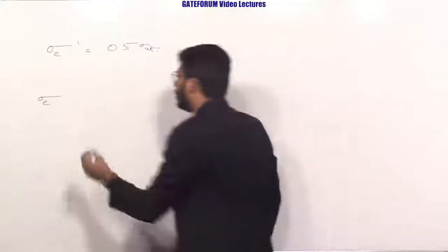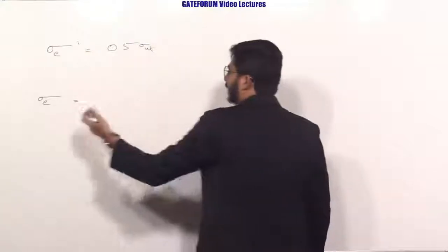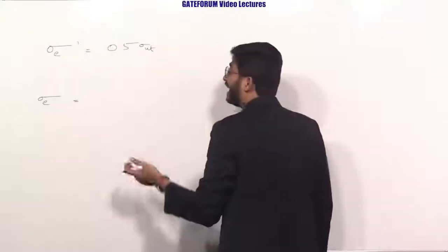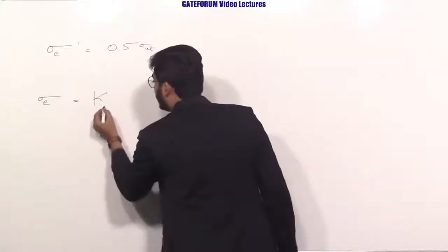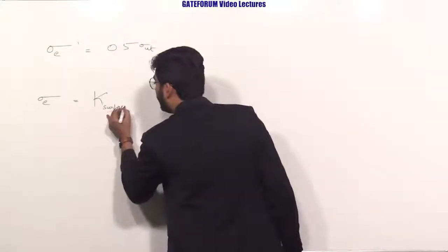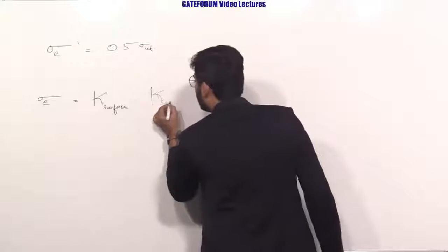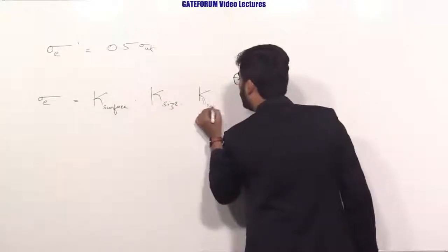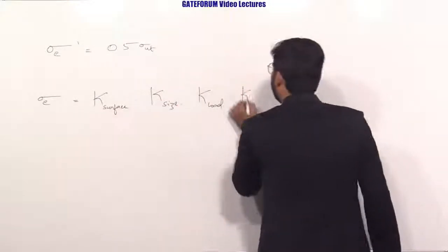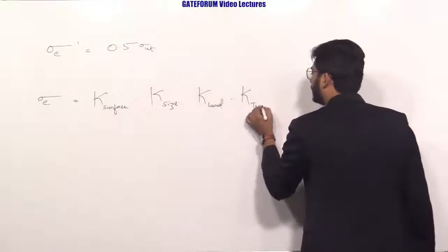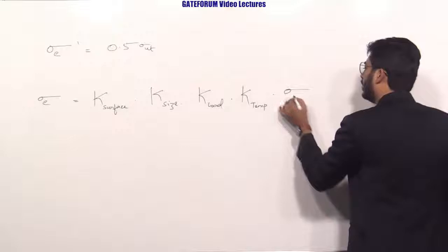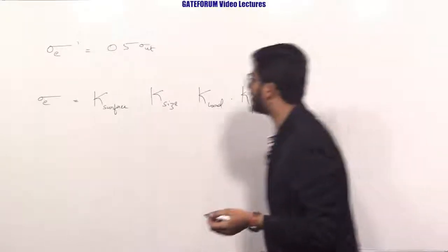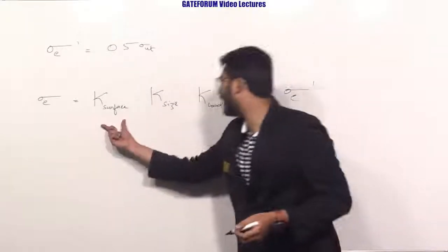So now when you are checking the corrected endurance strength, there will be the factors K surface, K size, K load factor, and K temperature, and reliability factors will also be considered here. So our discussion is with reference to surface and size.